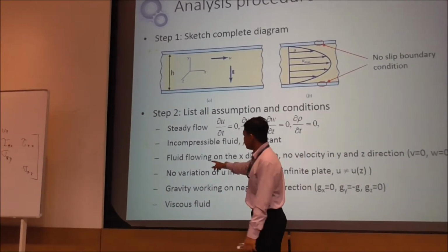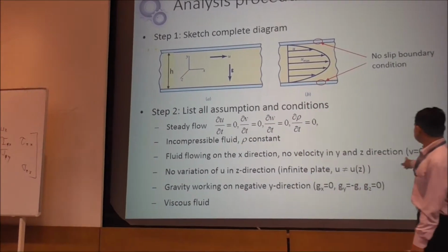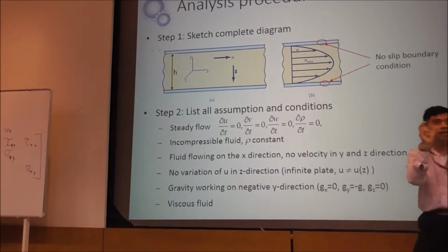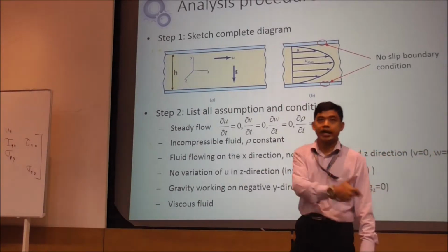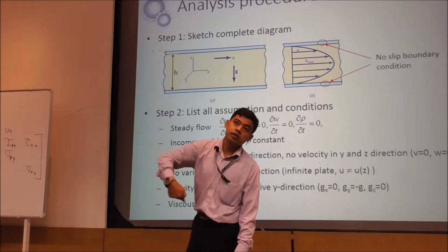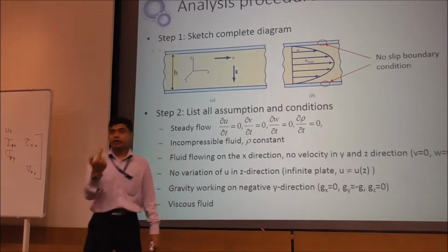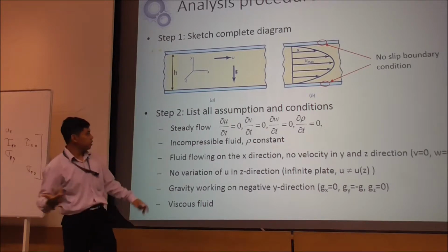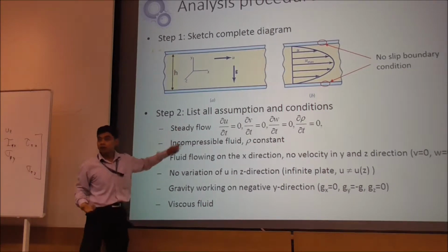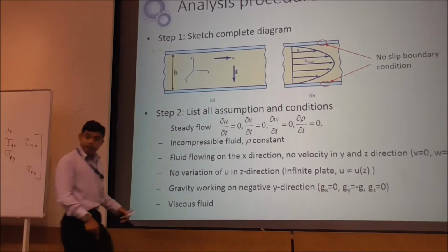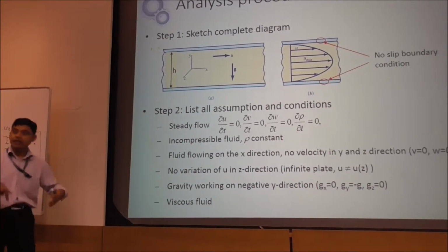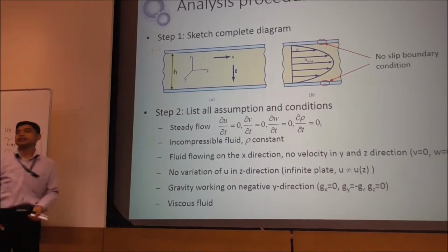So you can see, even though v and w are 0, u is not only a function of x. It can be a function of z and y. Luckily, it is not a function of time, right? Because it is steady flow. Otherwise, my speed here 1 second ago would be different from my speed here 2 seconds later.